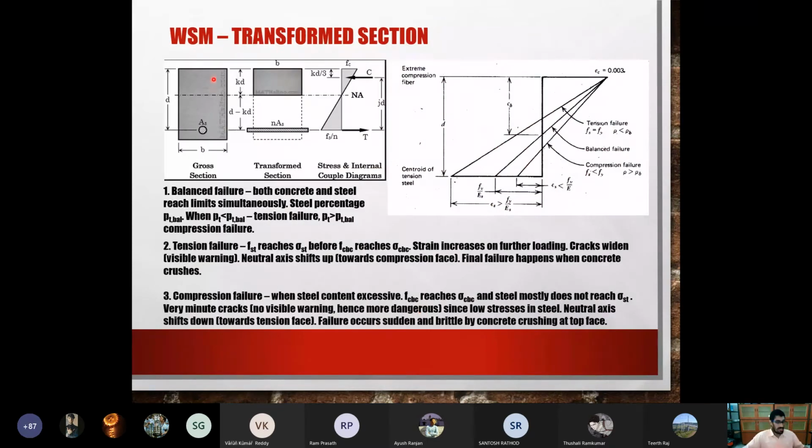Okay, so now as I told you, you have this concrete beam, and here only one reinforcement rod is shown, but usually you will have 3 or 4. You will not have fewer than 3 rods at the bottom of any RCC beam. Whatever is above this dotted line is the neutral axis. Above it, you can say that the concrete is there. Below the neutral axis, where you are assuming tensile stress, you assume that there is no concrete and only the steel rod is taking the tensile stress. So top compression, bottom tension. That's why C and T.